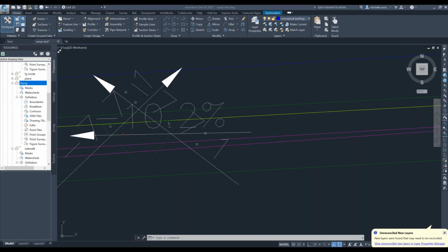As you capture it in the field, if you capture all the top backs of curbs and then all the flow lines, and since you're focusing specifically on the ADA ramps, grabbing where that flare starts and ends and where the ramp is, you could have it automate all of that line work. When you bring that into the model, it draws all that line work and you can create your surface from it and then have a nice surface to work with to start adjusting.